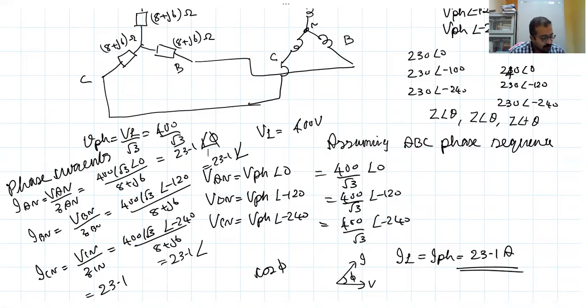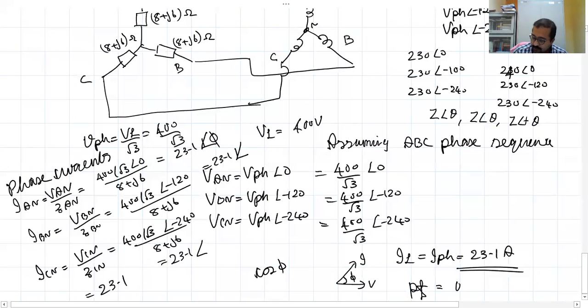That will give you the power factor, and that turns out to be around 0.8. You should get a power factor angle of 36.86, so approximately 0.8 lag.